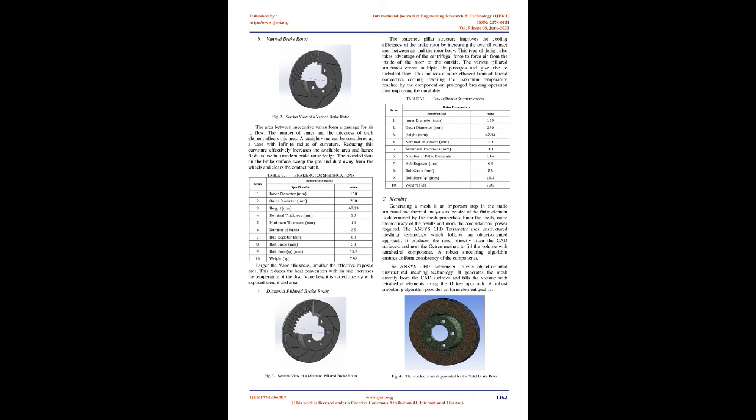6. Heat flux on each front wheel is applied on one side of the disc on the swept area, in a direction normal to the friction surface. 5. Radiative heat transfer is included in terms of an equivalent radiative heat transfer coefficient. 7. In this paper, we have considered single-stop braking scenario where the vehicle is at 120 km/h, 33.33 m/s, and the brakes are applied to observe the structural and thermal behavior of different types of disc brake rotors.